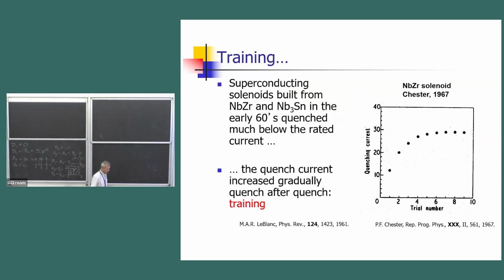The question though, and that's how we will get to margins and stability, is can you actually reach these values in a magnet? So we know what Jc is, we know what Ic is, we know what the Ic relation to field is. Now, if we push and ramp the magnet all the way up to critical current, you will get a certain field. Can you get there? That's the question I want to look at now.